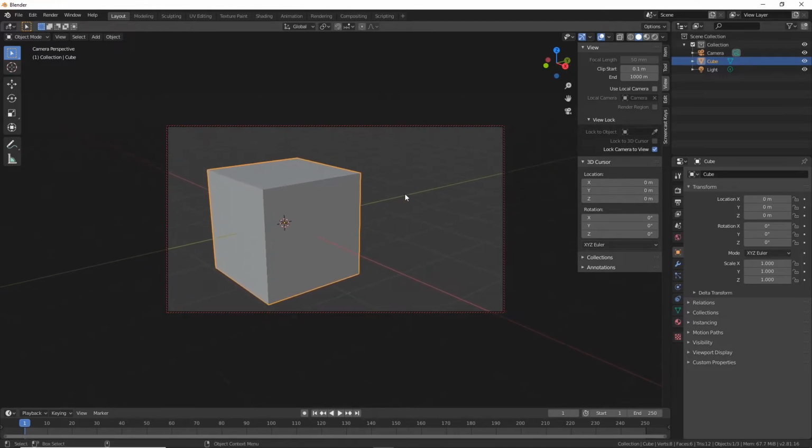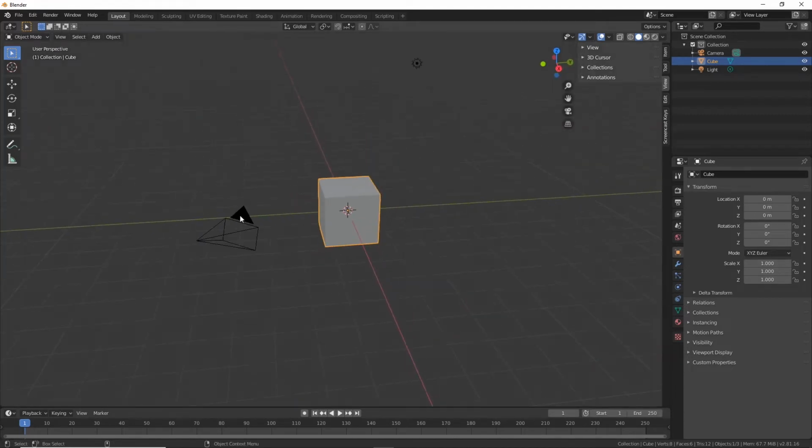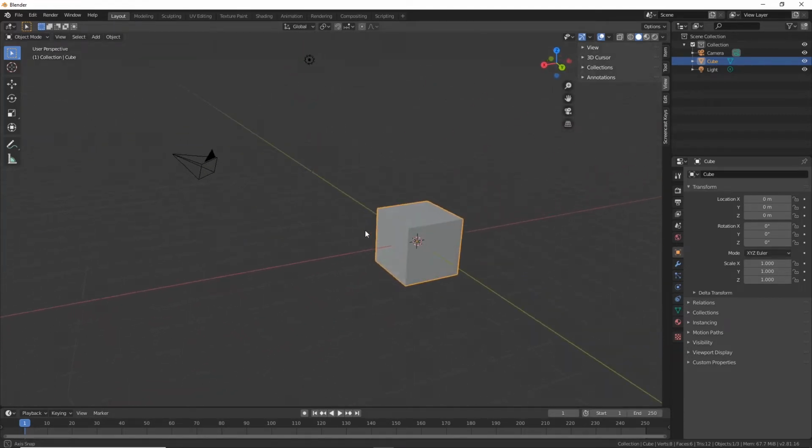All right, so once you've got that positioned and you don't want to stay in this mode and you want to leave the camera where you had it, you can turn off this little check box again under the tab over here for view. Just turn that off. You can close this up to minimize it. And now when I hit Alt, I'm going to move out of that camera, and there's the camera the way I positioned it. All right, so that's basically just manipulating the camera and setting up a scene.